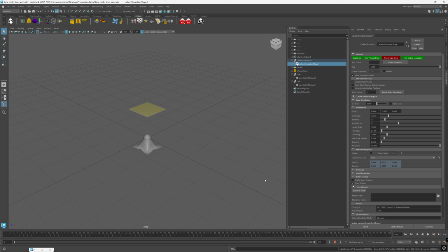So now you might wonder, why not just change the gravity in here? Well, this does not only affect gravity, but everything that has to do with acceleration or velocities. So you would do this when the animation is coming in at a different frame rate than what the timeline is. For example, your timeline is 24 FPS or 30 FPS here, but your animation was done in 60, and now it basically plays twice as fast in here. So then you could use your timescale to set it to 2 to make the simulation understand that your animation is actually twice as fast. Let me show you another example.